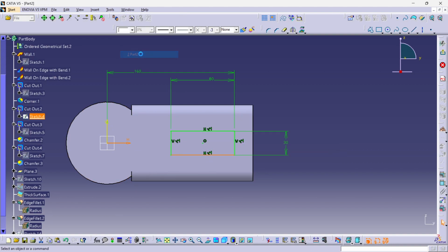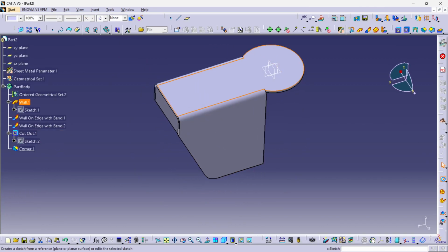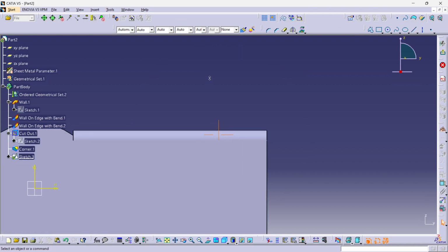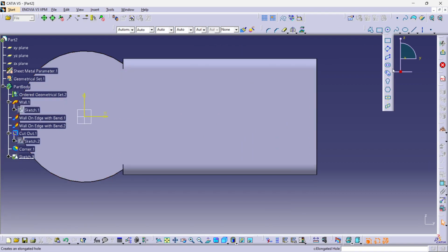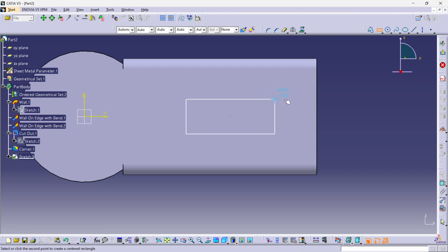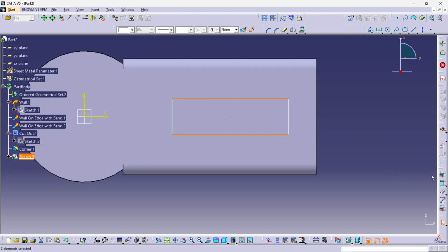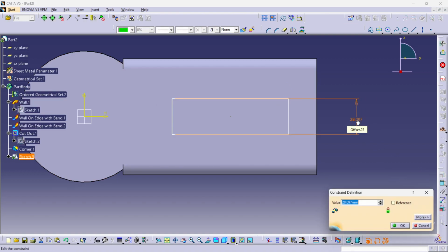So there's one good thing which is this one. Click on this, go for sketch. There's one rectangle which is centered, right? That is this one, center rectangle. This is a very good operation, I would say. So let's just follow the line. If you see the blue line, click on this, expand it, and good to go. Just make it as 30.